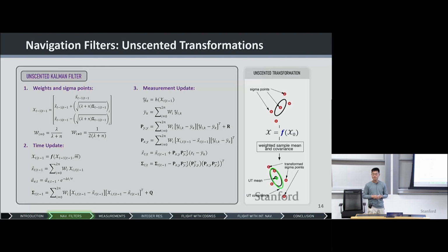An important consideration depends on the choice of your state representation. There are trade-offs. You can make the dynamics much more linear by using orbit elements as a representation, so you don't need a UKF there. The EKF does a good job for an orbit element state representation.